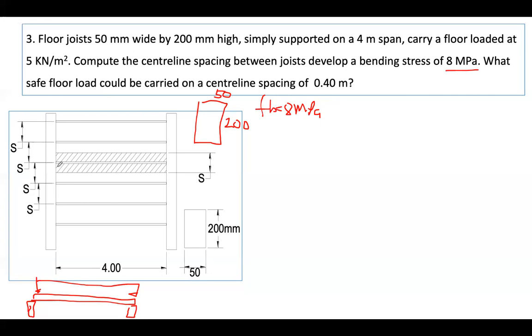As you all know, the floor joist is transferred to this beam, and then the beam will be carried afterwards by the column. So if you have here this floor joist, the tributary area, or the area being carried by that joist, is this one, as shaded. This is actually 1/2 of S here, and 1/2 also here that follows. This is just also the same as S.